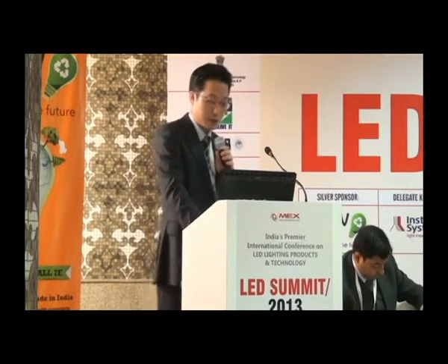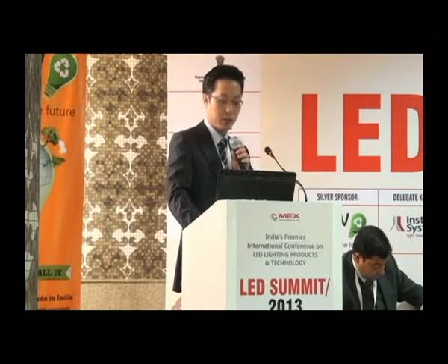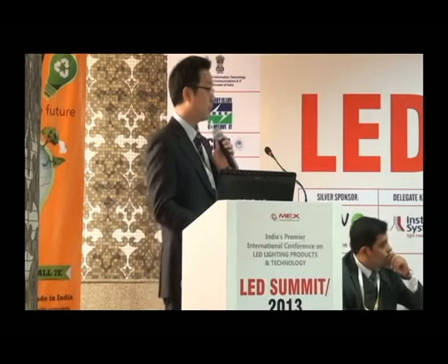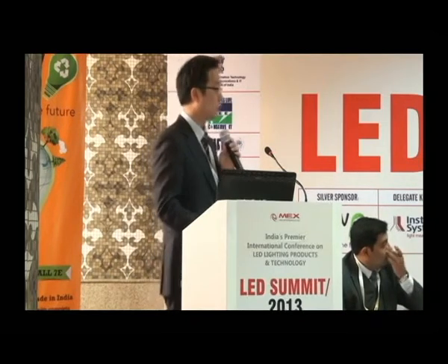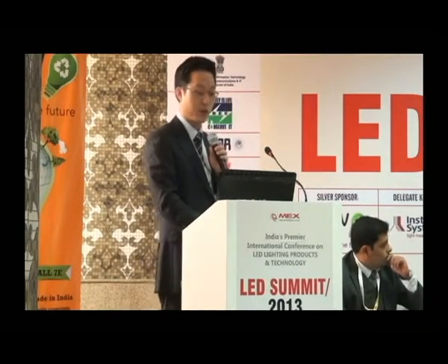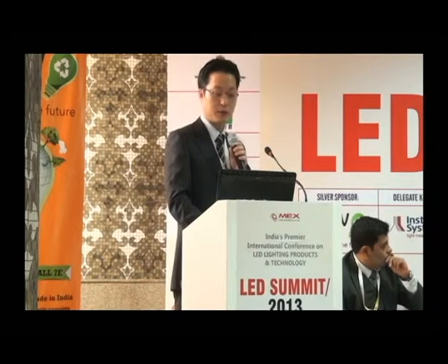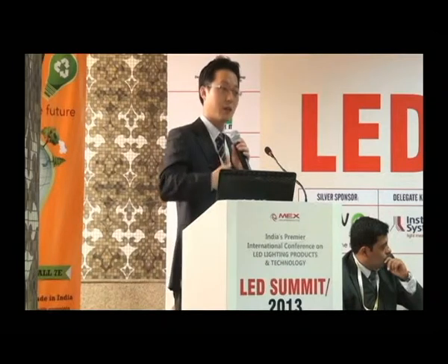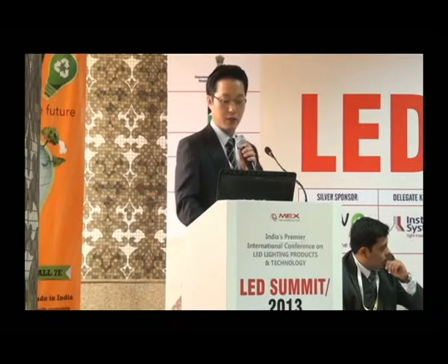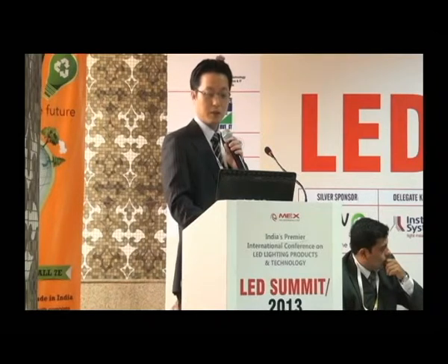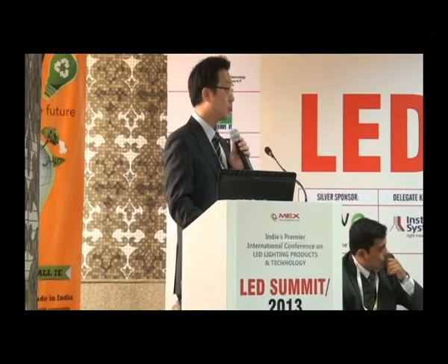First one is light extraction efficiency, because as you see, phosphor material has a refractive index of 2.5, but silicone material's maximum refractive index is just 1.53. That gap causes loss, because of the difference between the refractive indices, light reflects, and that gives a loss of light efficiency. So the target is increasing the index, but there is some limitation of silicone chemistry.